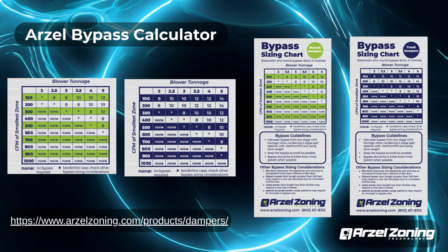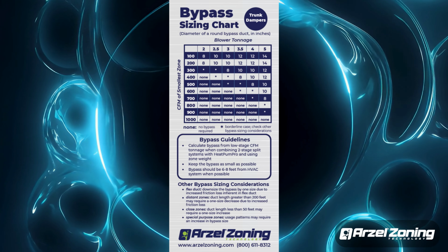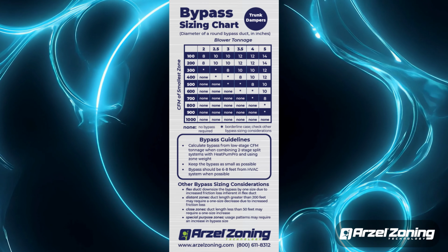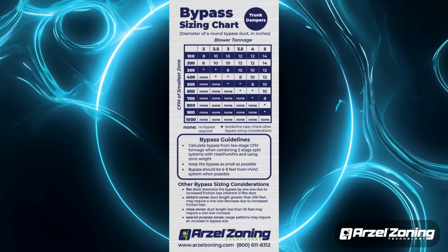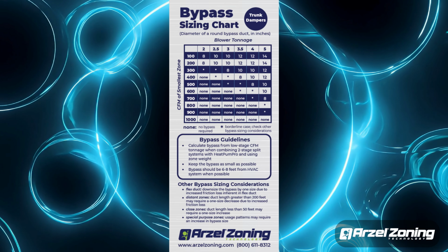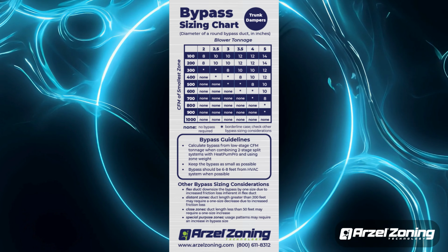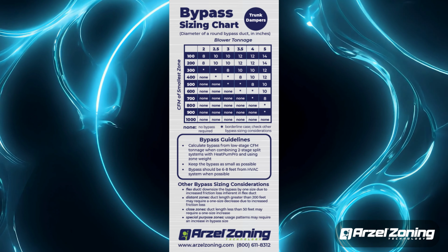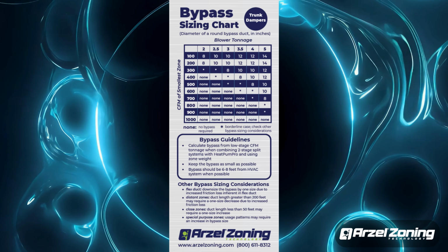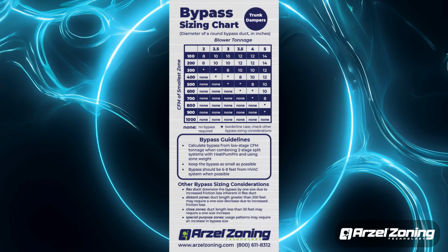Now, just to do a quick calculation here, go to the trunk damper side of the bypass calculator, and what we're going to do is take a 300 CFM zone with a 3-ton system. What size bypass do you need? 8 inch. Now, what if my 300 CFM zone was on the other end of the house and it was all flex to get there? What I suggest is figure it, quote it, order it, get it to the job, but don't install it till you commission the system and see if it's objectionably loud. And your customer should be the one to determine if it's too loud.